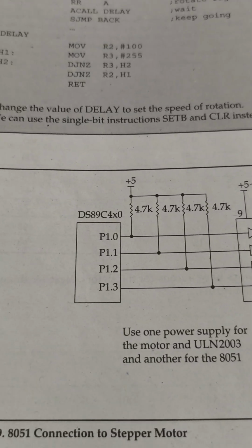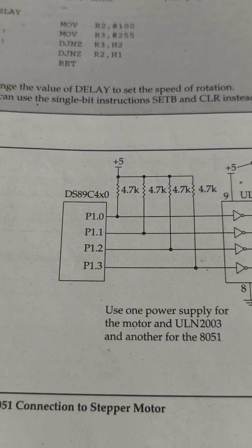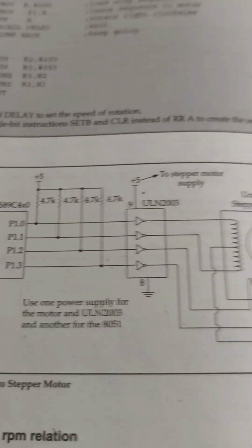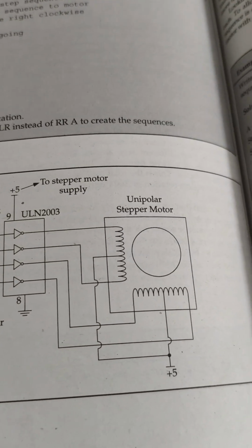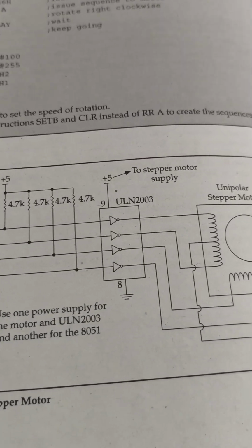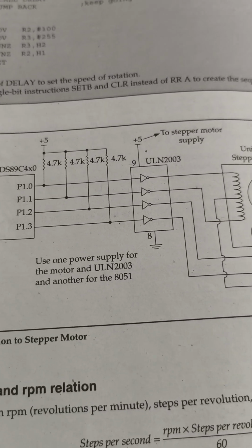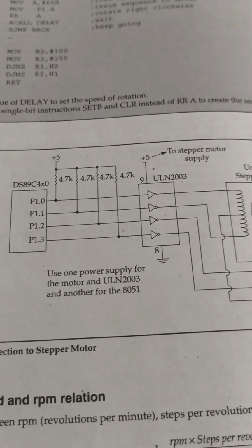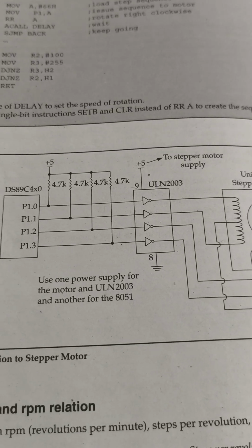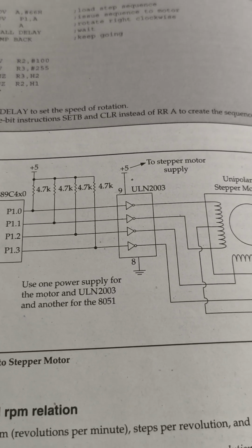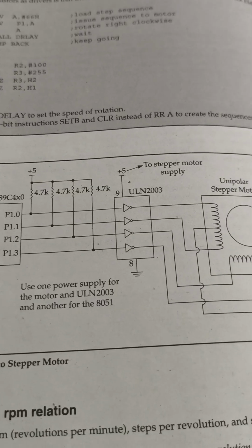This is your microcontroller. Here they have used a different microcontroller. To that microcontroller we interface the stepper motor. Then we have to give the signal through the ULN. We use one power supply for the motor and ULN 2003, and another for the 8051.